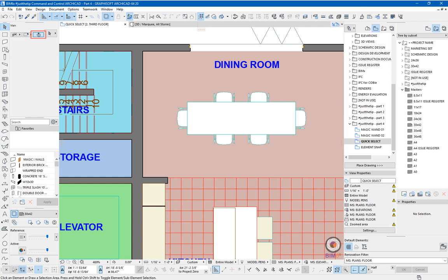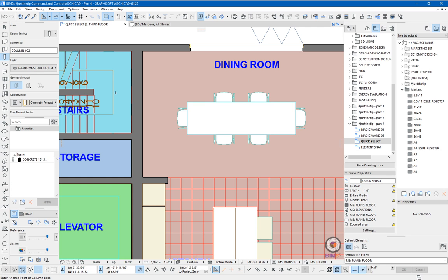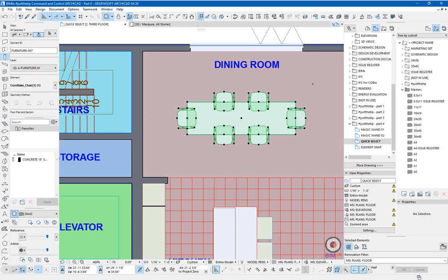So if the mouse, whatever tool we're on, or even if we use the shift key, which is one of the previous videos, but whatever we use to try and select something, straight away the little magnet icon appears, and ARCHICAD is telling us that there's something below the mouse and it's giving us information about it. So even if I'm using the shift key, I can still hold space, and that disables quick select. So I'm then free to go around, select this without worrying about picking up anything else that's underneath there.